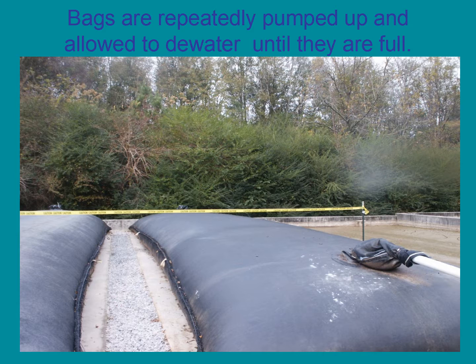The bags are repeatedly pumped up until they are full of dewatered solids. In this setup, a gauge line is installed over the bag to tell the operator when he has pumped the bag to its maximum design height limit.